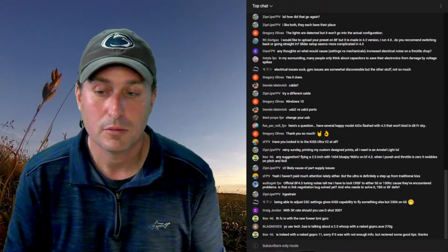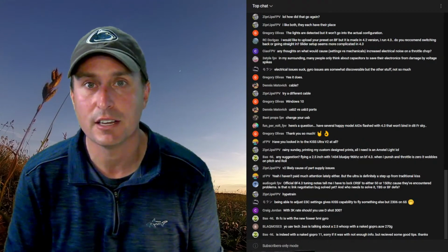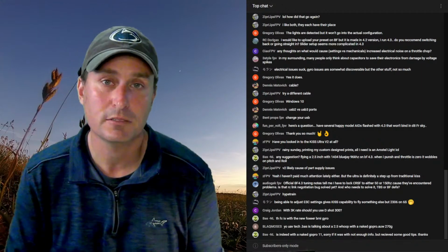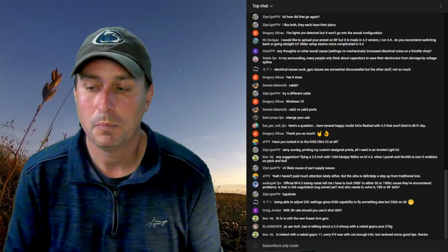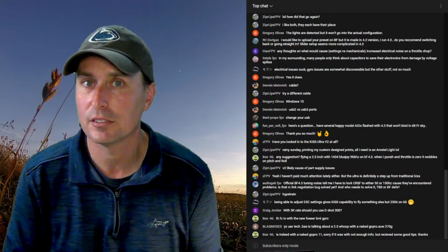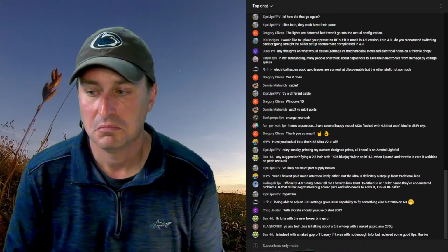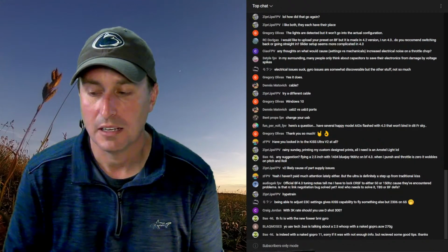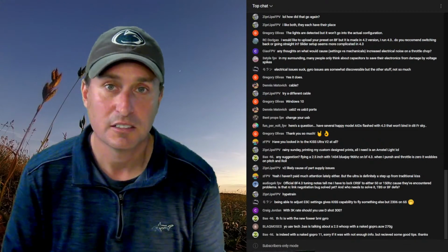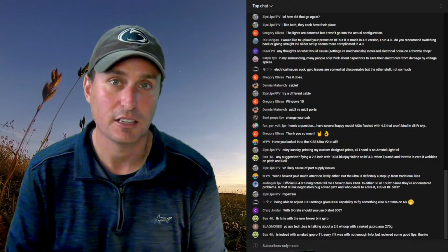So what happens with Crossfire is that Crossfire really touted that it's the fastest control link back in the day, like 5 years ago. And it was true. But the 150 hertz mode is very short range. As in, you go 100 yards away, or maybe not even 100 yards away, it jumps to 50 hertz mode.